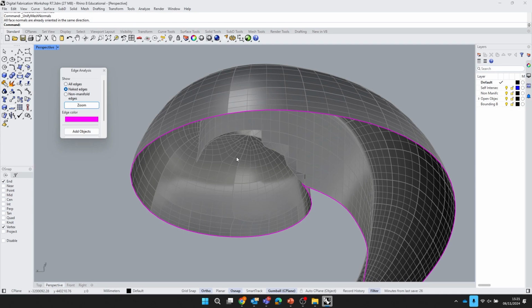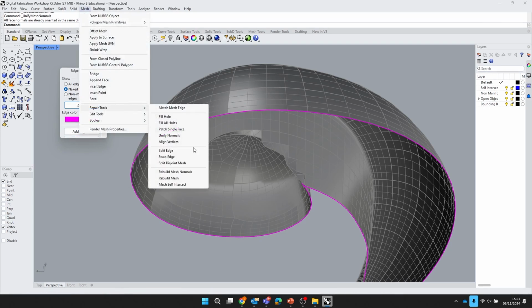So when you rebuild, what is rebuild? Can you just explain those three steps? Yeah, so essentially what it's doing at each step, when I go to repair and go to rebuild mesh, is kind of resetting the mesh itself, how it's built. If everything's been joined together, it will remember that they used to be separate pieces. But when you do rebuild mesh, it'll almost delete the original and rebuild it fresh. It will renumber each vertex in order, make them all nice and clean, and say that's now one new object, effectively.